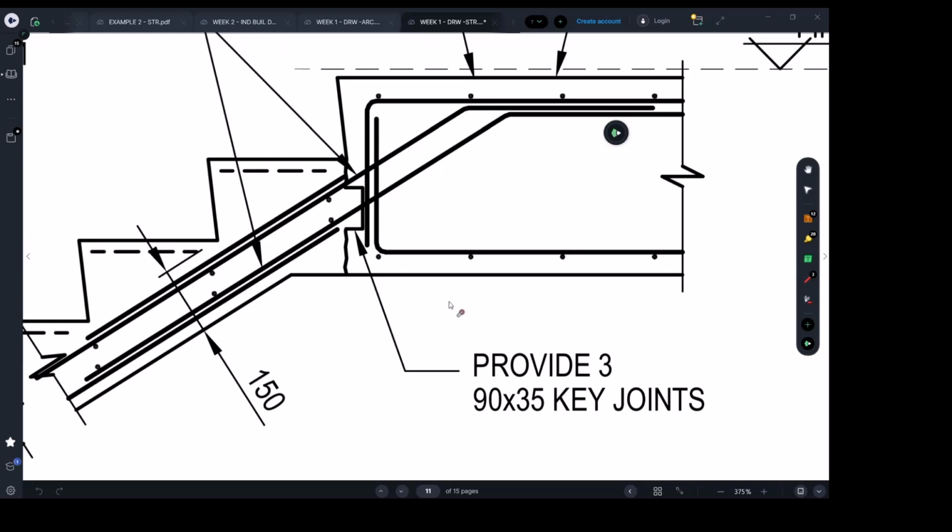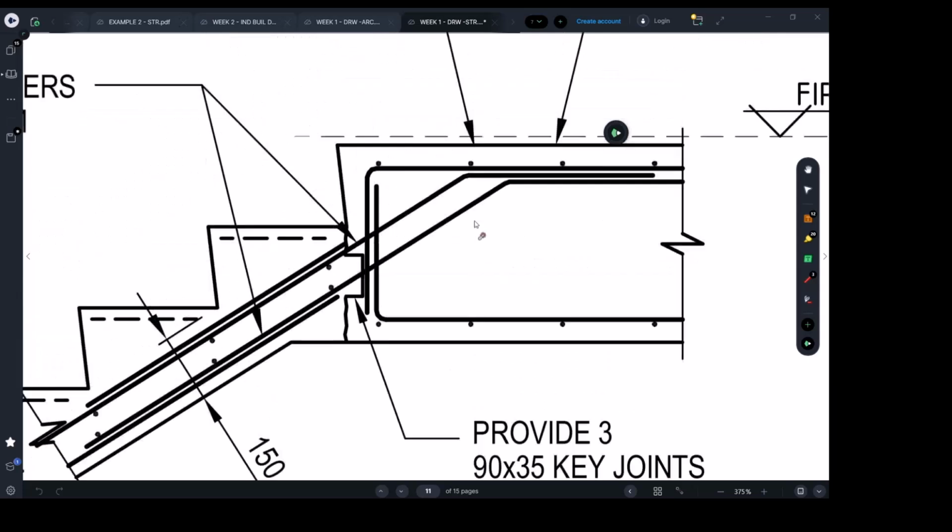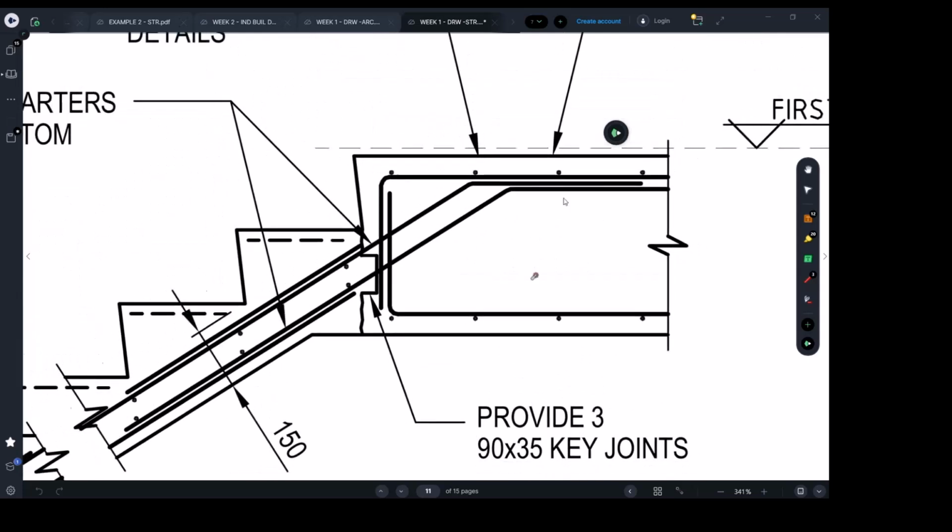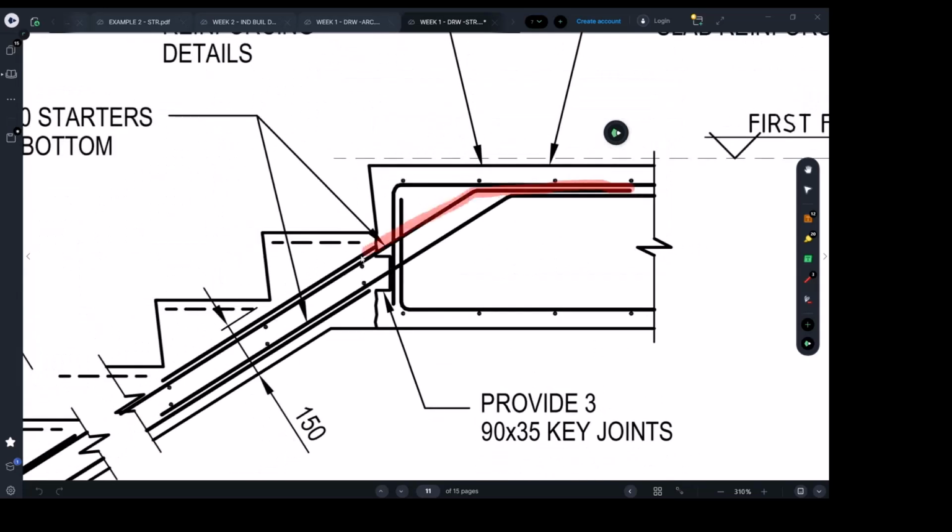These kind of questions, that's what you're going to see in the final exam, right? That's exactly what you're going to see. Steel bars for the stairs should be put beforehand in the beam, which is anchoring. Excellent. So there are anchorage or starter bars, whatever you call them. There are these bars. You see them? You have to make sure you remember these bars.